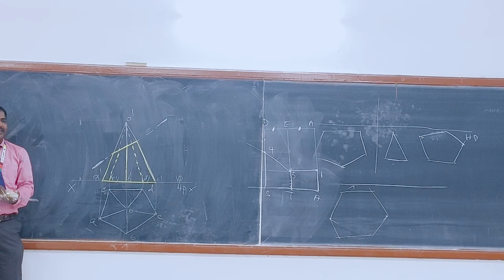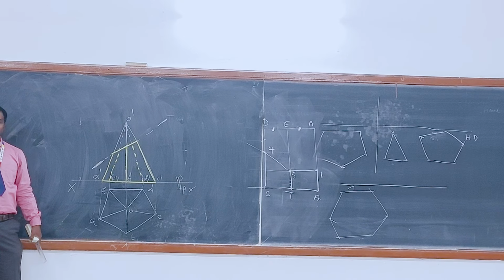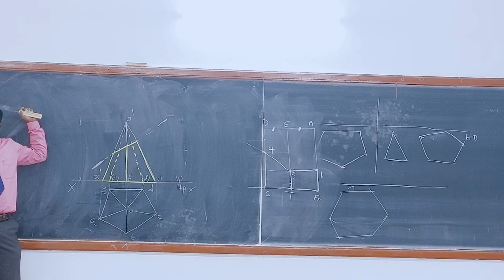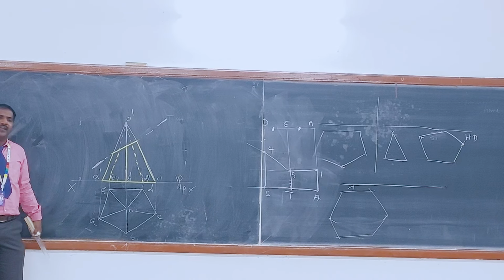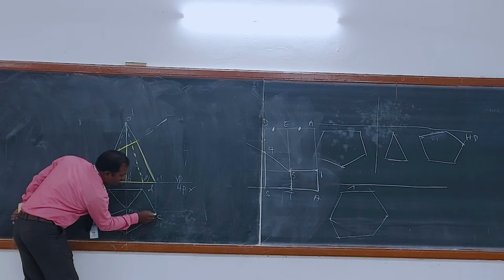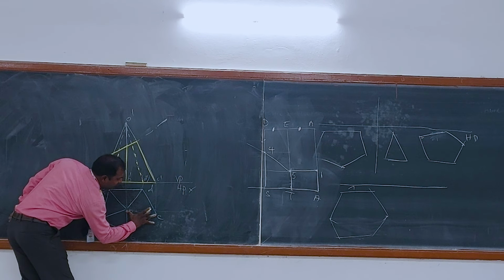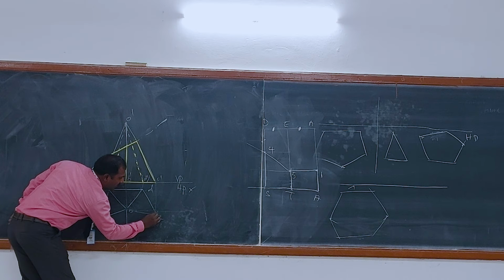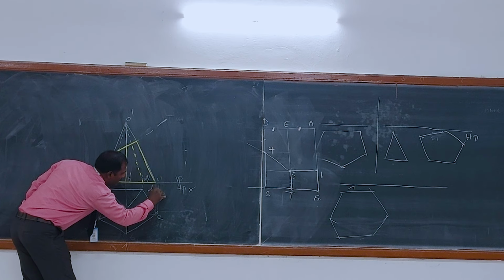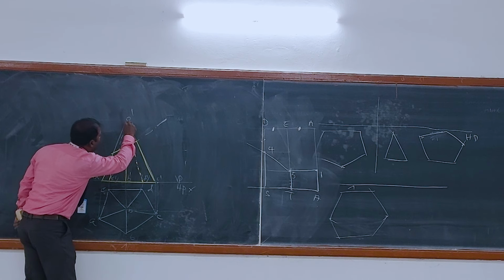In such a case we have to form the true slant edge, as already mentioned. If there is one, we can go directly to the problem, no doubt. If not, we have to create the true slant edge. Draw one horizontal line from this place, take this distance, draw the arc. It will cut here. From this point draw one vertical line, extend here, join this point and your apex.